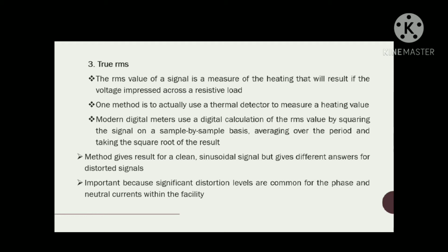These different methods all give the same results for a clean sinusoidal signal, but can give significantly different answers for a distorted signal. That is the point. This is very important because significant distortion levels are quite common, especially for the phase and neutral current within a facility.